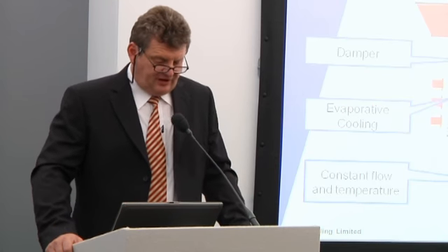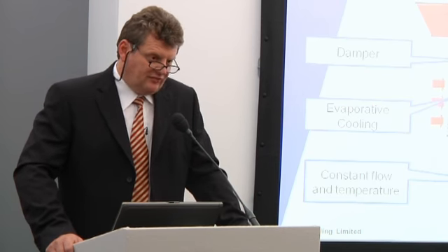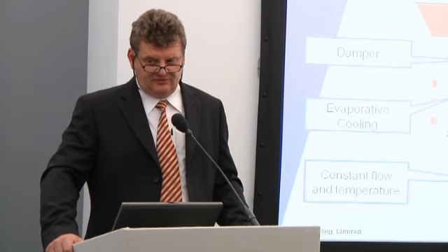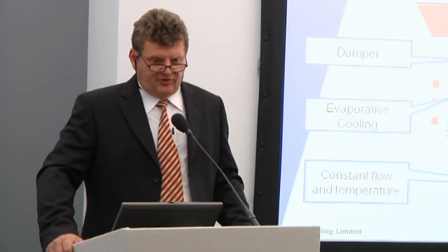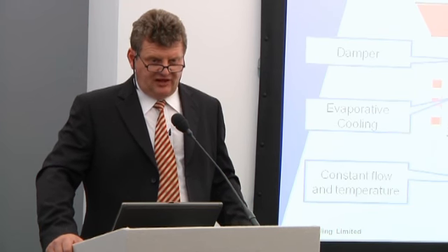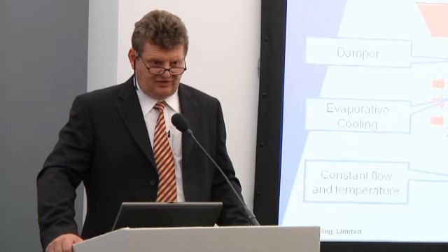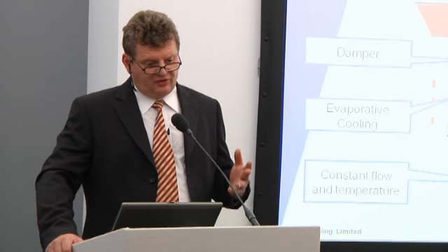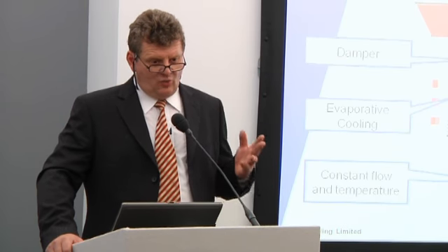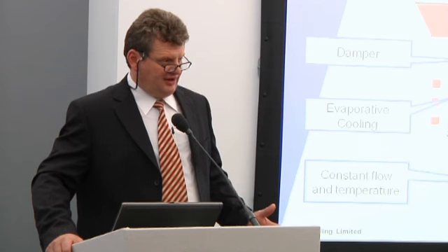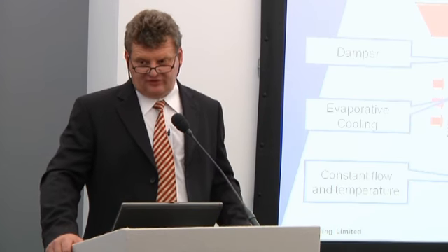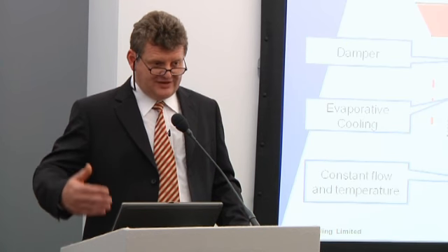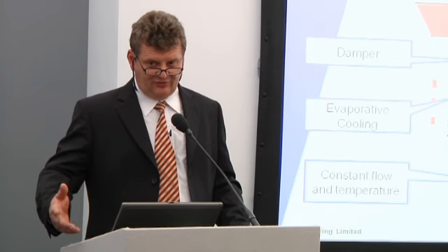Just as a slight aside, when we commissioned M247, we started with a set point of 20 degrees centigrade. As time's progressed, we've actually reduced that, and it's now running at 17 degrees centigrade. The net result of that is, whilst we're achieving the cooling savings, we actually reduce the net IT load as well by running the servers at a lower temperature. So the PUE looked good, but also the net use of the IT went down as well.